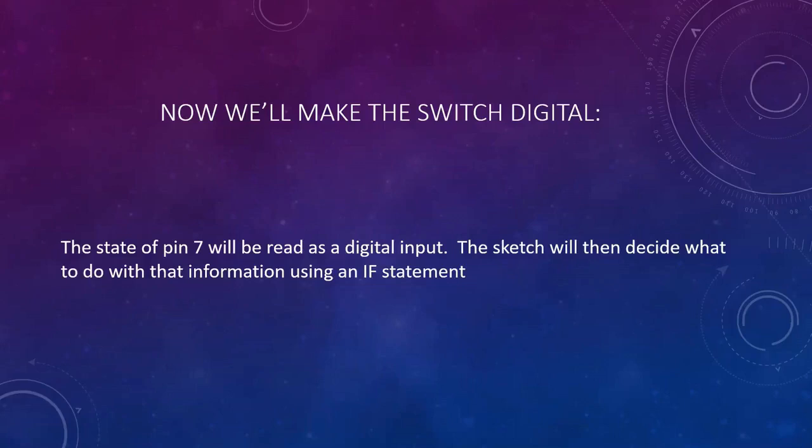That means that the switch can be on or off, and it doesn't actually change anything about the buzzer and LED circuit. It's completely disconnected. It's a different thing altogether, and that's nice because you might want to be able to do something like have the buzzer and light go off when the switch is tilted. Previously, we couldn't do that because tilting the switch disconnected the circuit.